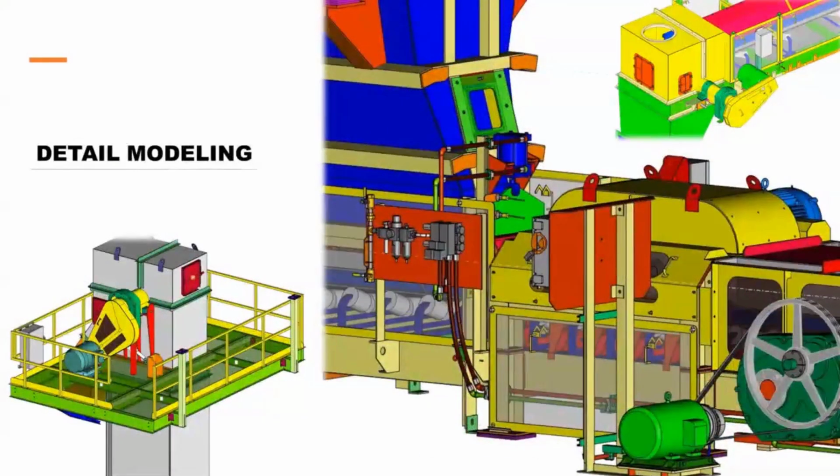Those concept models that start out pretty basic all get broken up into individual 3D models, and those models become very detailed. And we try to provide an accurate model that is an exact representation of what's going to be fabricated. This limits the amount of fit-up mistakes, it eliminates the potential problems that are going to happen, and it helps guarantee that the customer gets what they expected to get out of us, and we provided that.